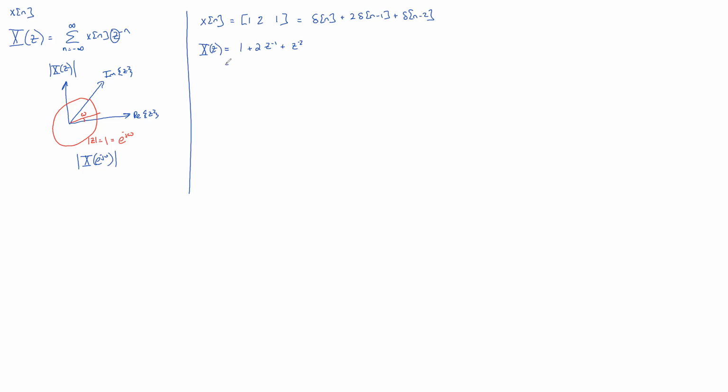The answer comes if we write it differently. Remember, there's different ways to write this in different notations. One is in Z to the negative 1, but the other is in just plain old Z's. And writing in plain old Z's, algebraically the top is the same thing as the bottom, just a different notational style. And then what is this for Z equals 0? You can see this blows up. And it's the only finite Z for which this blows up. So we'd say that this is true for all magnitude of Z greater than 0. That's why it blows up at 0. Does that make sense, Eric? You divide 2 by 0 and you get infinity.